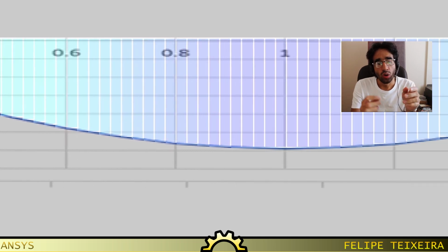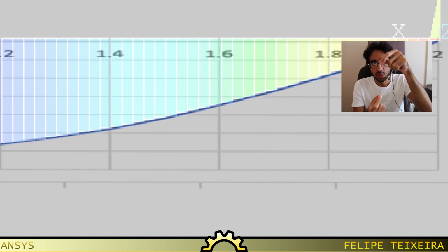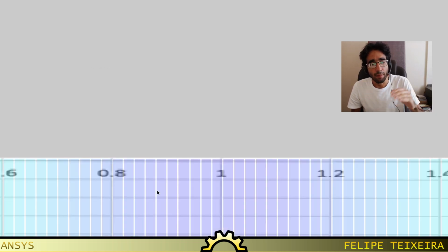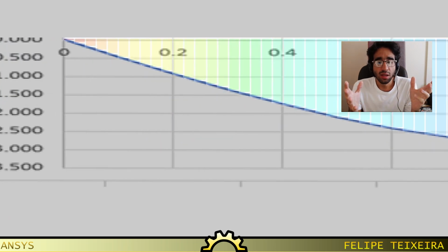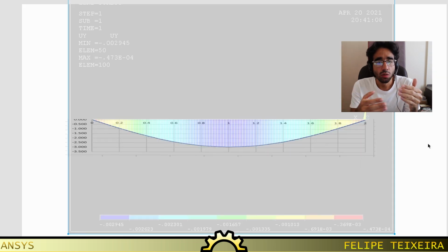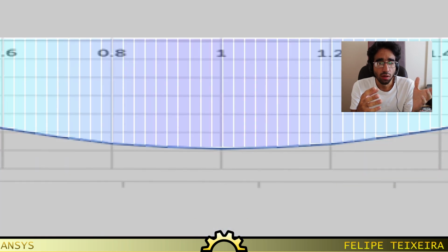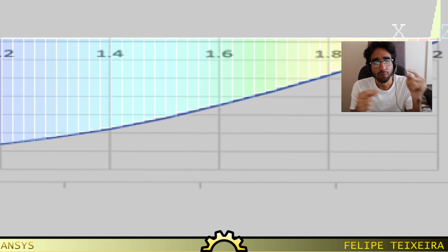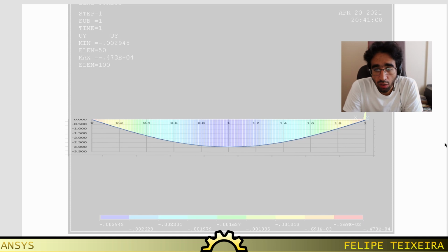And here you can see the result. When I make the beams match horizontally and at the maximum point, the curve itself, meaning every point along the analytical elastic curve, matches one of the colored ANSYS bars. So obviously I can't be too precise with this comparison. I'm just making a visual comparison, but at least I can show you that the results mostly match. If there was any difference in the shape of these curves, this difference would be apparent here in the superposition, or this difference is way too small that I can't even detect it when I make the length and the height match. So that's the final demonstration of how our analytical results match the results we obtained in ANSYS, both in terms of maximum value and in terms of the shape of the elastic curve.